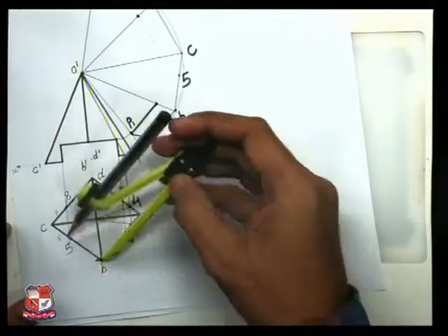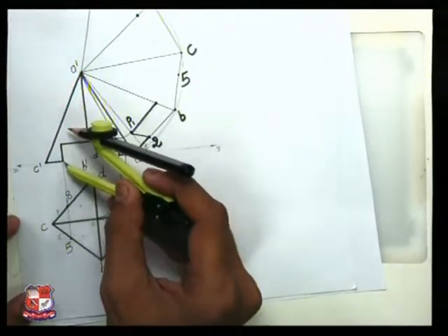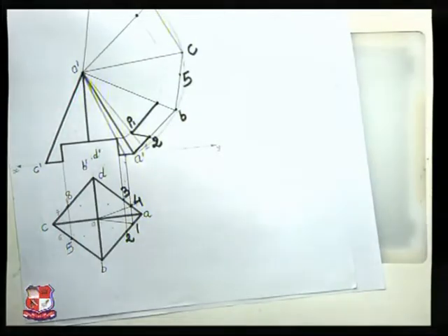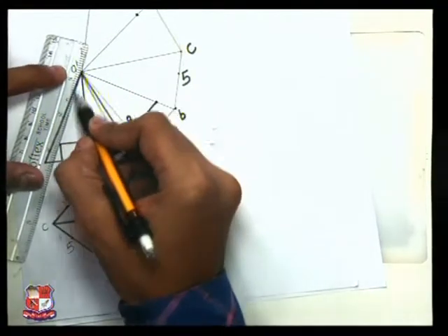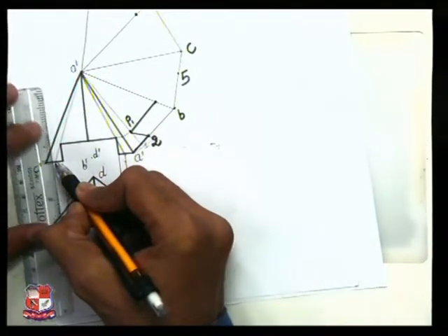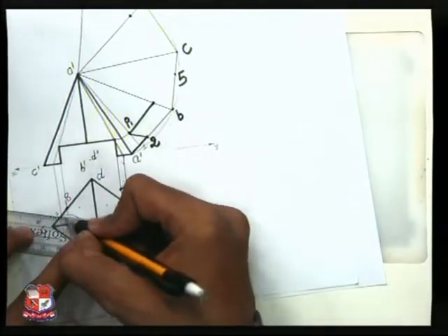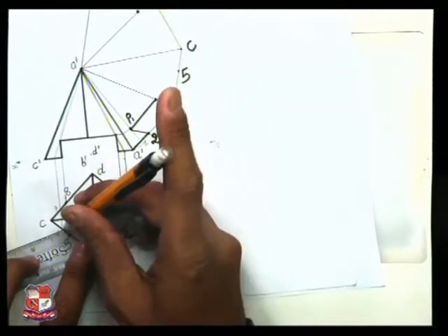These B5 and B5 distances are the same. Now this point here is the generator. So this is 1 point. Now what about this point? For this point, draw an imaginary generator like this. Transfer that point to its top view and join this apex point to this, like this, to show the top view of the generator.